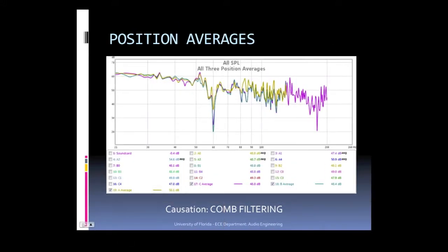The results of our experiment can be shown in the following graph, which displays the average of 5 measured values for each tested position, in order of highest gain, the subwoofer placement in the front corner of the test room, to the position with the lowest gain, when the subwoofer was placed 3 feet towards the center of the room. Although there are multiple reasons for the results in this experiment, a prominent cause could be the effects of reverberation and a signal processing phenomenon known as comb filtering.